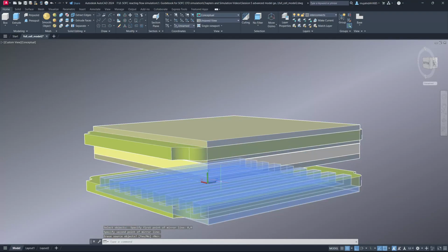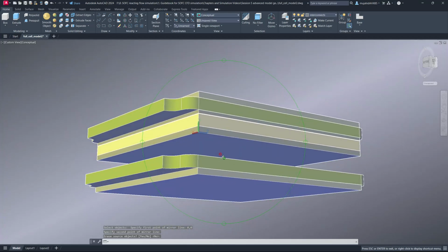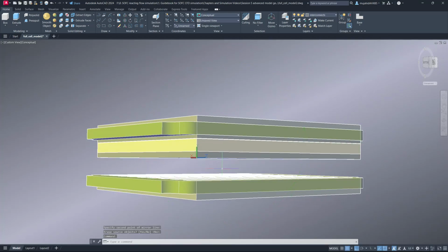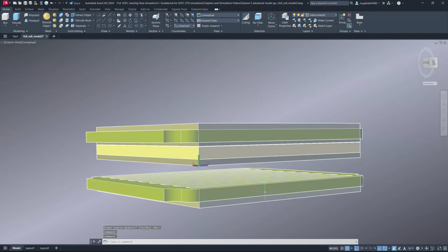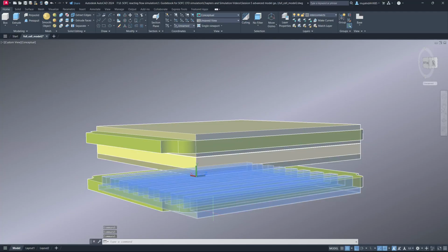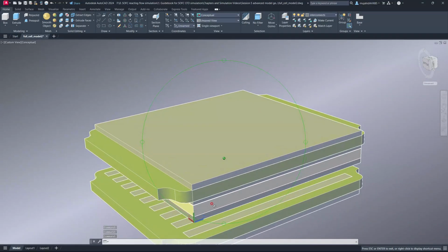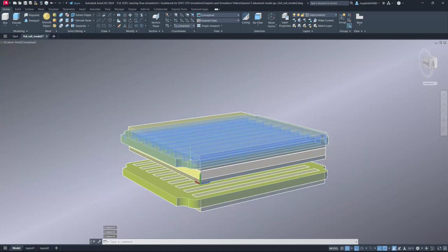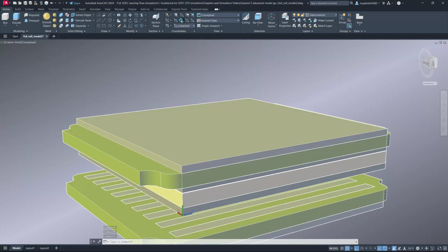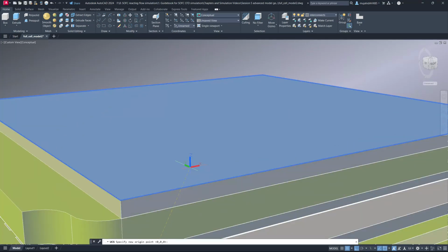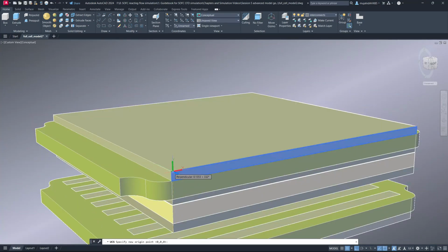The next step is to give a proper orientation, because they are not in the same direction. We want the anode side, the hydrogen fuel flow direction, to be the positive x direction, so we need to rotate it by 90 degrees, but the rotation axis is also at the center, so we should first take the orientation and have the snap.